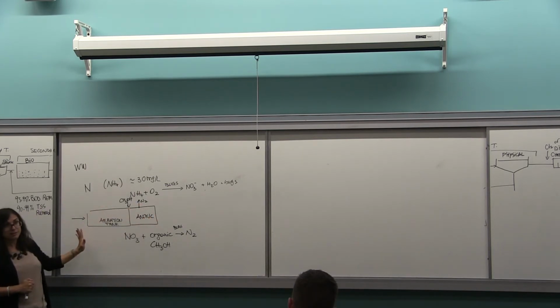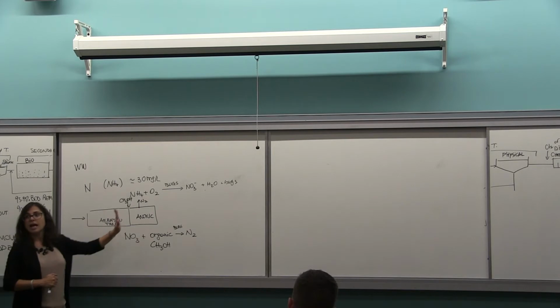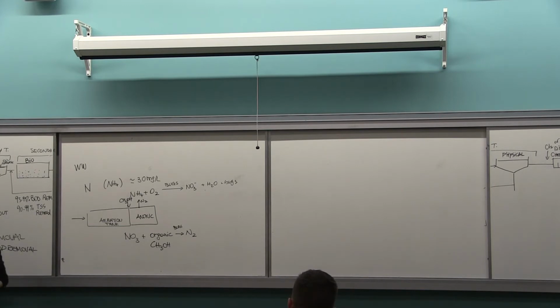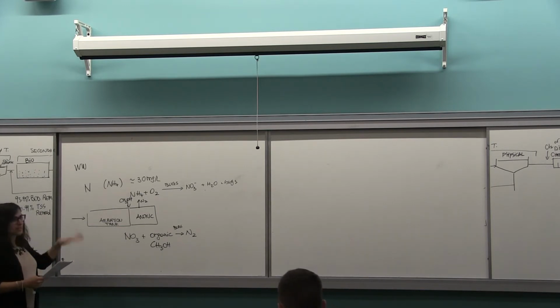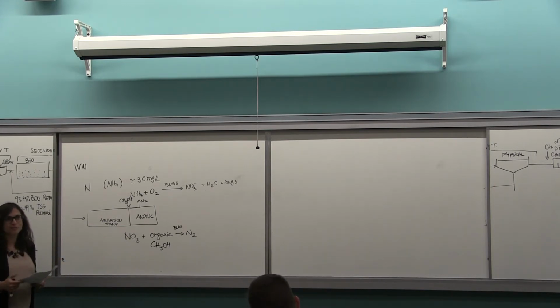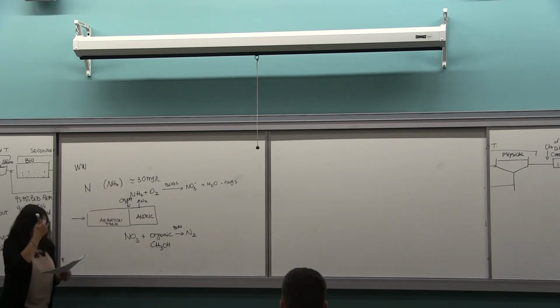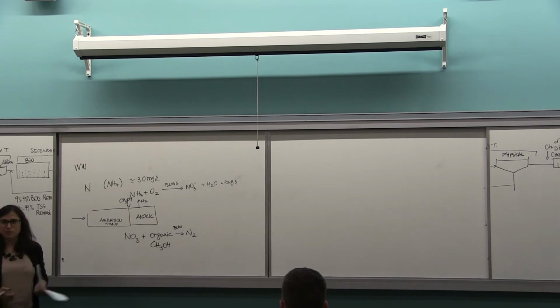I add air and convert, then I add methanol and convert nitrate into nitrogen gas. So this is the concept of nitrogen removal: nitrification, denitrification.